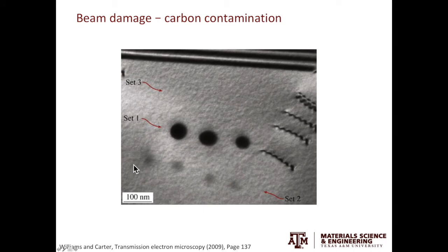Another thing that is worth mentioning here, but not really a result from the inelastic scattering, is the carbon contamination. Because inside TEM the vacuum is not perfect, by dwelling the beam at the same spot for a long time, you can see those carbon contamination on the specimen surface.